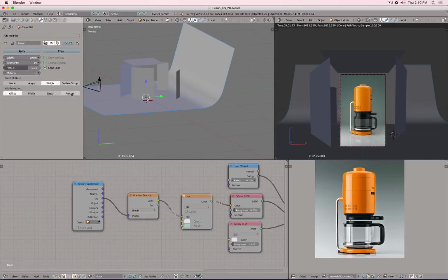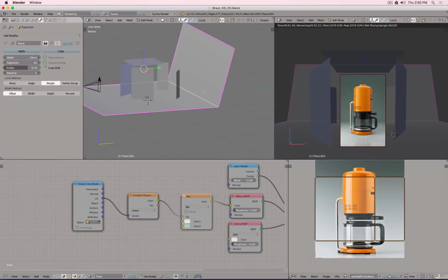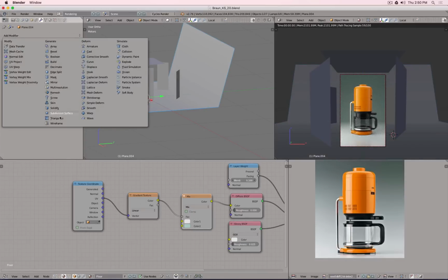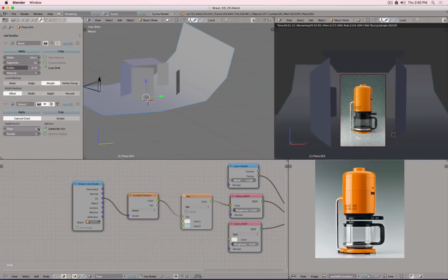So this doesn't really work well, so I can turn this one off. You notice I still have these outer edges sharpened or creased, Shift E 1. And let's add a subdivision surface modifier. So maybe go to 3. And there you see now how nice and smooth the color transition is, because the object continuously bends.